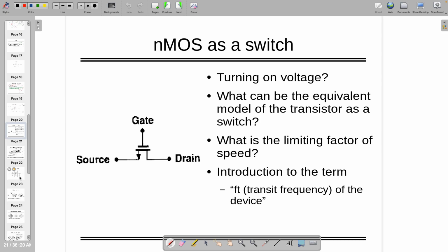Okay, so now before going into transistor as an amplifier, let's go to NMOS. This is true for PMOS also, but you can learn it through NMOS as well. So NMOS as a switch. Wherever in any book you are seeing this symbol, understand that the 4-terminal body is connected to ground in the case of NMOS, and in the case of PMOS, this is always connected to VDD.